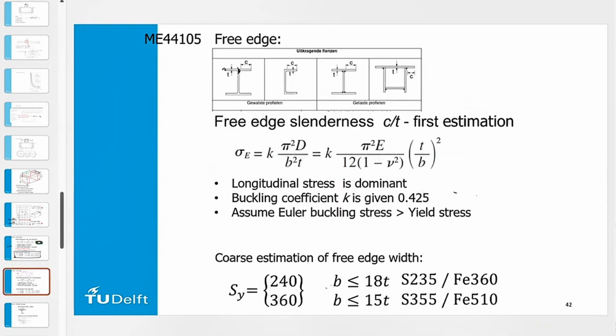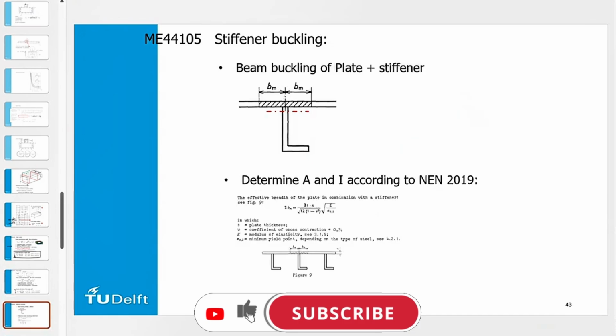If we need to take that into account in the Eurocode, for example, then of course these limits are the upper ones. You still prefer yielding over buckling. So instead of these top limits, you use something which is slightly lower.